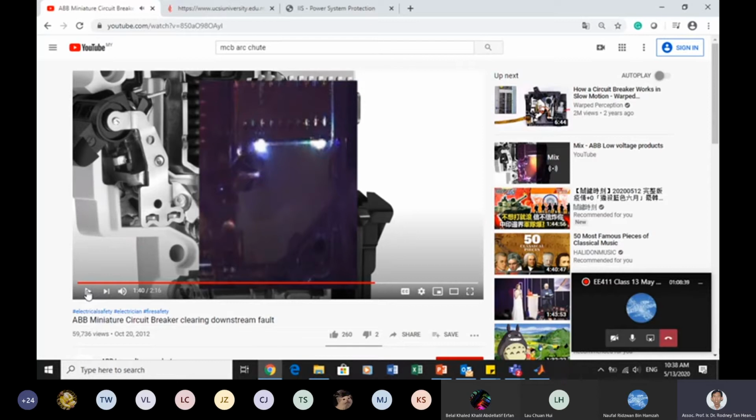So it took around 3 milliseconds. Okay, now you can see the arc will try to re-energize again in between. So you see, just now I showed you the counterfeit one. I'm not sure, but this one has 12 pieces, and they only put like 6 pieces, half. So it may take longer than 3 milliseconds for the arc to be completely extinguished.